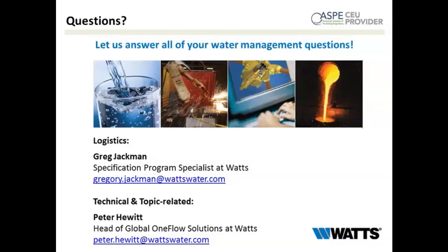Do you base replacement on pressure drop? Say that again, please. Sorry, do you base replacement on pressure drop? So there's less than 15 psi pressure drop through any series of TAC systems. So it's a very minimal amount, particularly when you're in front of booster pumps, which is what we recommend in high-rise buildings that have booster pumps. So the system would be ahead of a booster pump, and therefore pressure increases can be controlled. So you can use the less than 15 psi drop as a metric.